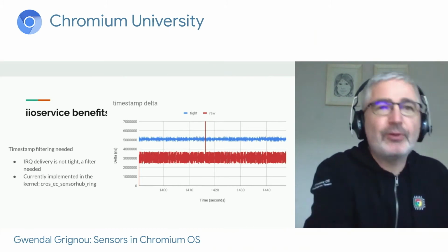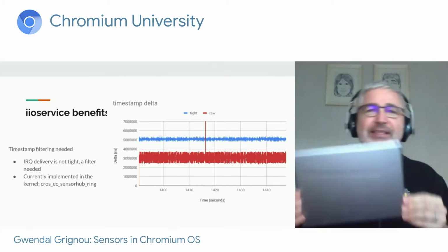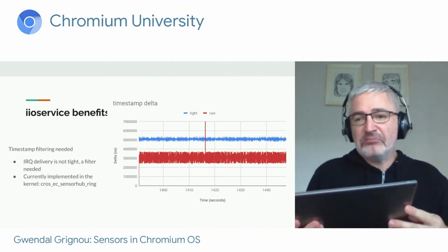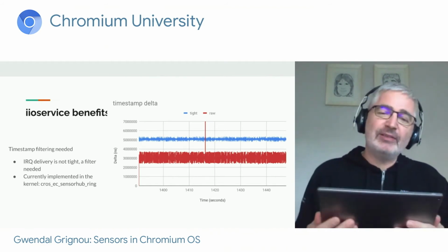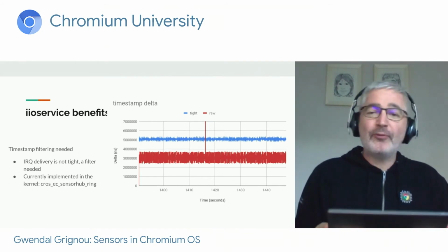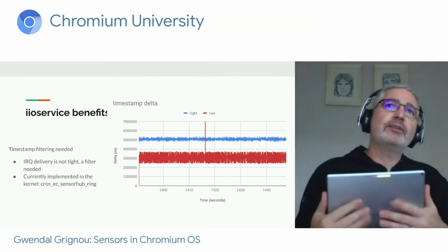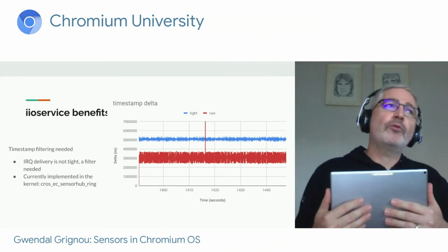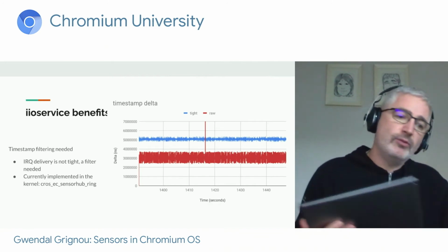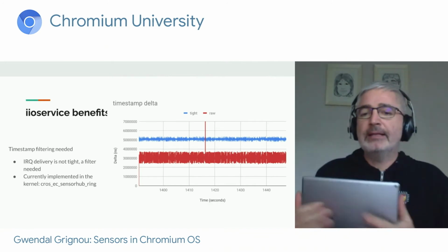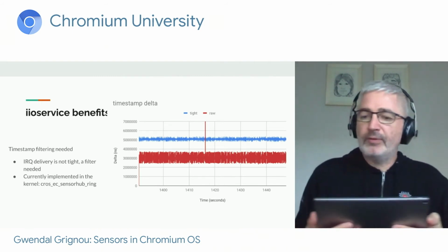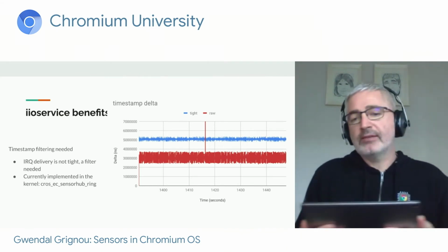When I first worked on the Pixel C about 4 years ago, the requirements for timestamping were not that tight, and we took some freedom with it, and we implemented the embedded controller without a hard IRQ from the EC to the AP, but using a soft IRQ via ACPI, and that introduced some variation in the latency.